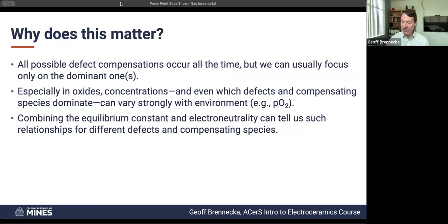Now you pull the oxygen out. If you've got titanium, oxygen, titanium, and you get rid of that oxygen, then these titaniums are going to shift over and be closer to the other oxygens around them, and the vacancy that is left behind is actually a little bit larger in volume. Conversely, shoving a titanium into an interstitial site, yes, it's going to pull stuff closer around it, but there are also other cations around, and those are going to get pushed away. So an interstitial will actually make the lattice parameter grow as well.